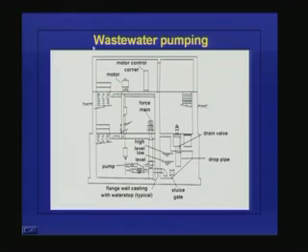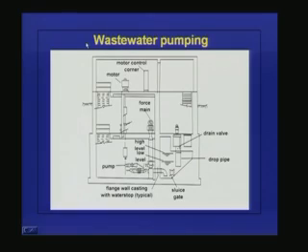Then in wastewater pumping, the principles of pumping are very similar, except that the quality of water is different, and the kind of issues that one has to consider is the release of gases from the wastewater, particularly when we are talking about sanitary sewerage. Or when we talk about a storm sewerage system, the intermittency in the operation is an important consideration.